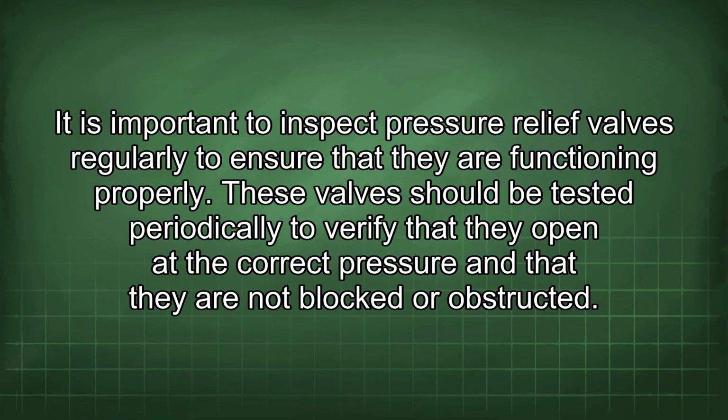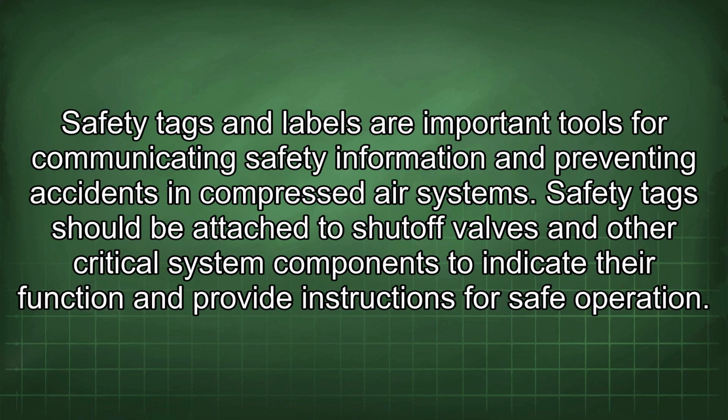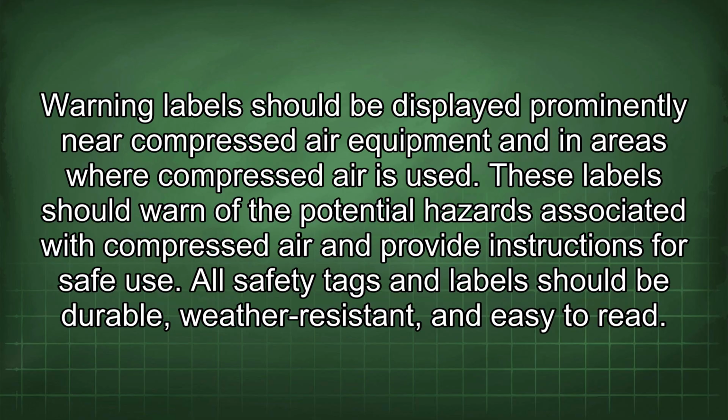These valves should be tested periodically to verify that they open at the correct pressure and that they are not blocked or obstructed. Safety tags and labels are important tools for communicating safety information and preventing accidents in compressed air systems. Safety tags should be attached to shutoff valves and other critical system components to indicate their function and provide instructions for safe operation. Warning labels should be displayed prominently near compressed air equipment and in areas where compressed air is used.